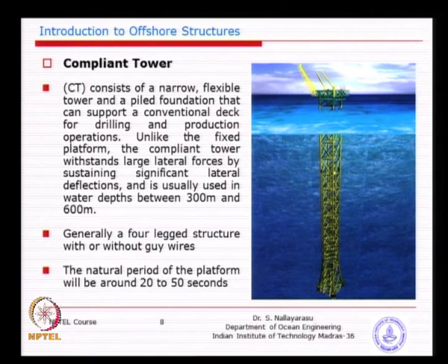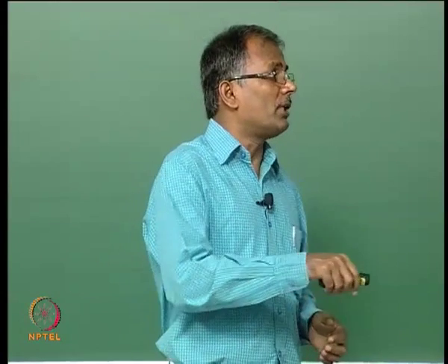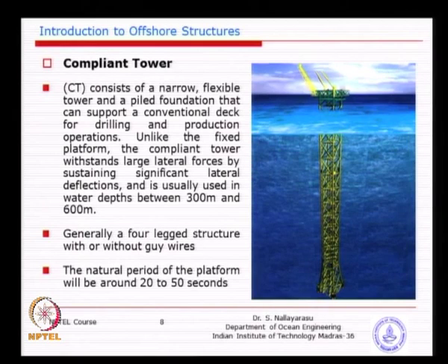So, here the manipulation of the structural system is done in such a way that the period goes beyond those 20 seconds. Sometimes we use tuned mass dampers in such a way that it takes you beyond there. So, manipulation of the structural arrangement could be made because it is very slender, and the mass system at the top matters: the larger the mass at the top, the more you will see the period shifting higher and higher.